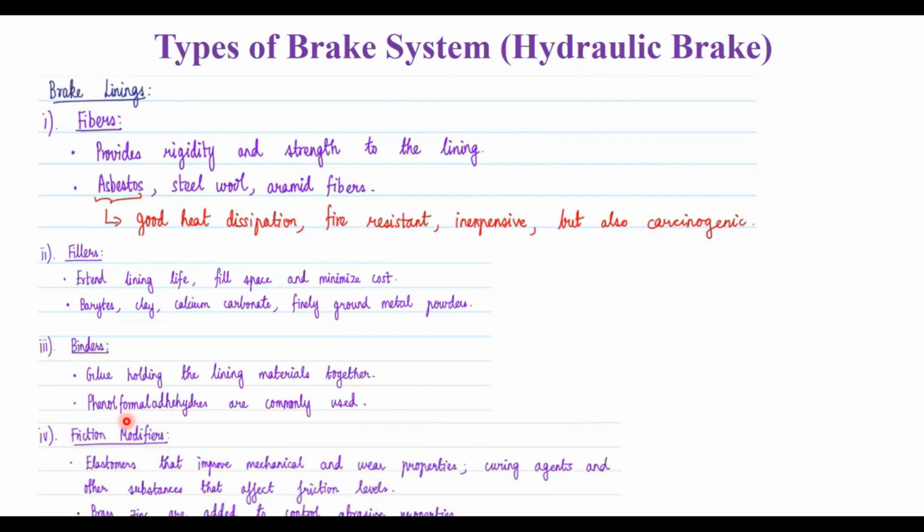And you have the friction modifiers as well. In the case of hydraulic brake application, the elastomers have been used, which will improve the mechanical and wear properties. And also brass and zinc have been added to control the abrasive properties as well.